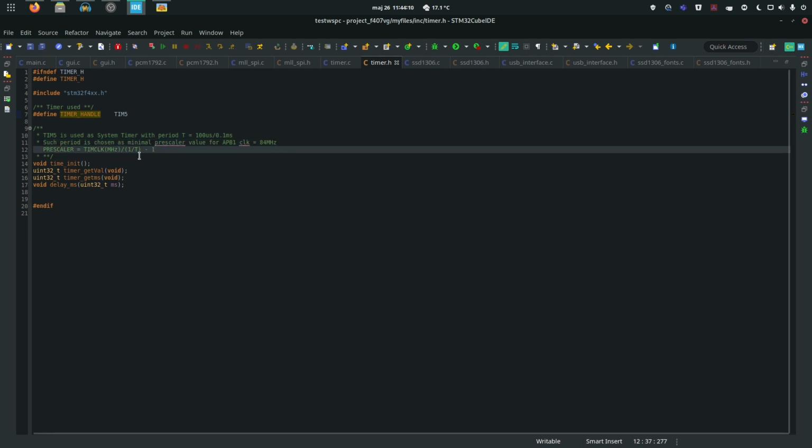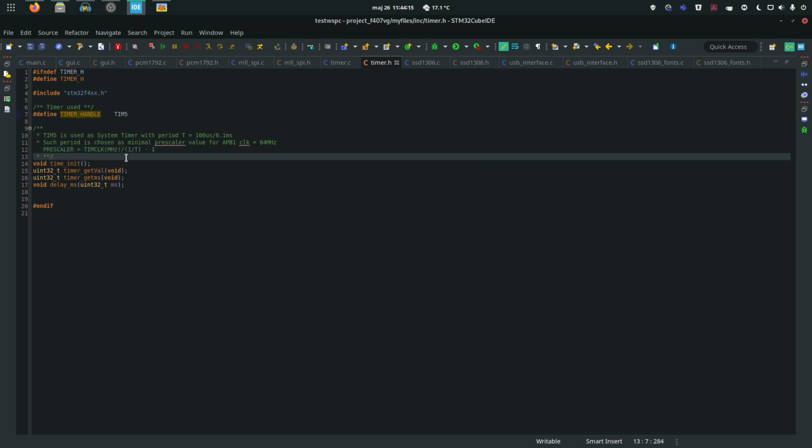Well, that's because in this project I'm using a simple version of RTOS for this school project as well. And the first rule of this simple project is also to not have external interrupts when doing RTOS programming, to create a better deterministic system. So you know that nothing else is going to interrupt the RTOS routine. Therefore, a timer that is used by HAL or even low level that actually initializes a particular timer in default setting is SysTick, but it could also initialize any other timer that you wish. It creates that timer interrupt.